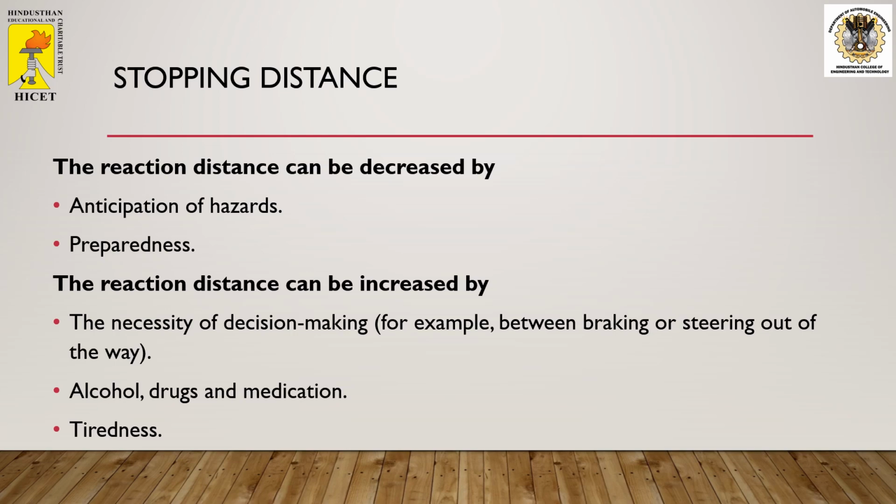But on the contrary, the reaction distance is increased because of confusion in decision making. Especially, the decision making should be very crisp, only then he would be able to properly stop the vehicle. Second is consumption of alcohol, drugs, or any kind of medicines which cause drowsiness. Because of these, the reaction distance or reaction time may increase. Then tiredness: if the driver is driving for a longer period of time, it would definitely result in fatigue. Because of this, the driver could not decide well, which results in increased reaction distance.